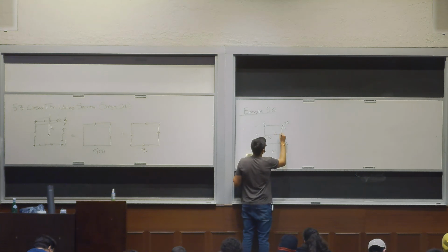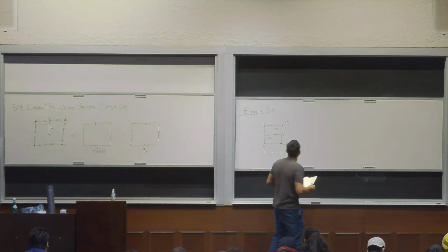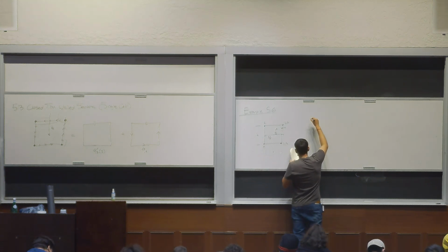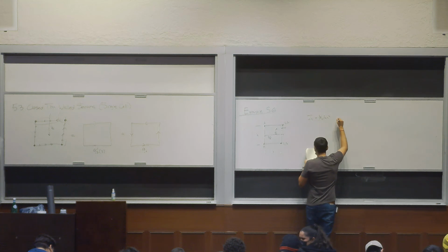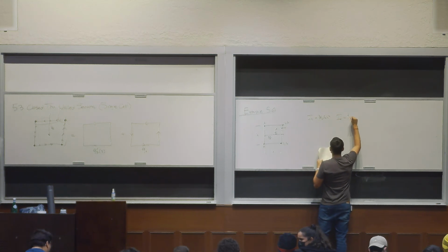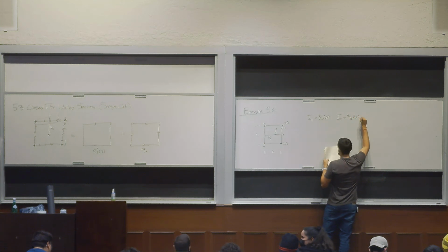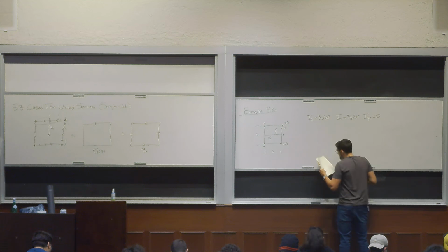And that's where you define your coordinate system. Then you find the moments of inertia. So we end up finding Iy equals 3/2 Ah squared, Iz equals 4/3 Ah squared, and Iyz is symmetric, so it's 0.